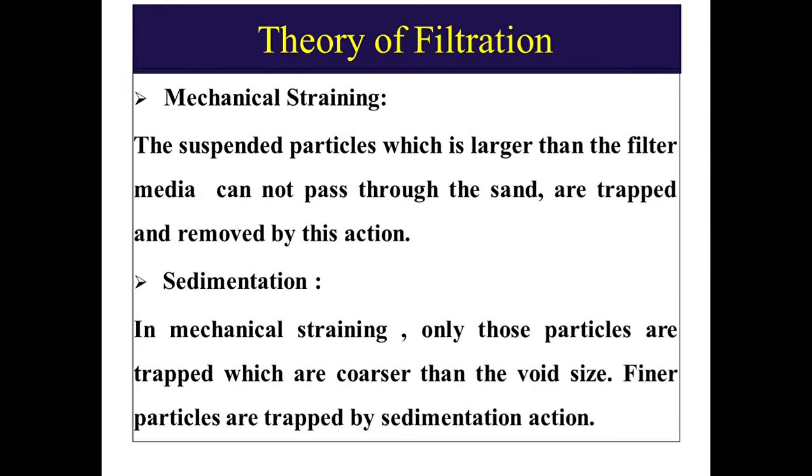First of all, what is mechanical straining? The suspended particles which are larger than the filter media openings cannot pass through the sand, and are trapped and removed by this action. Second is sedimentation. In mechanical straining, only those particles are trapped which are coarser than the void size. Finer particles are trapped by the process of sedimentation.